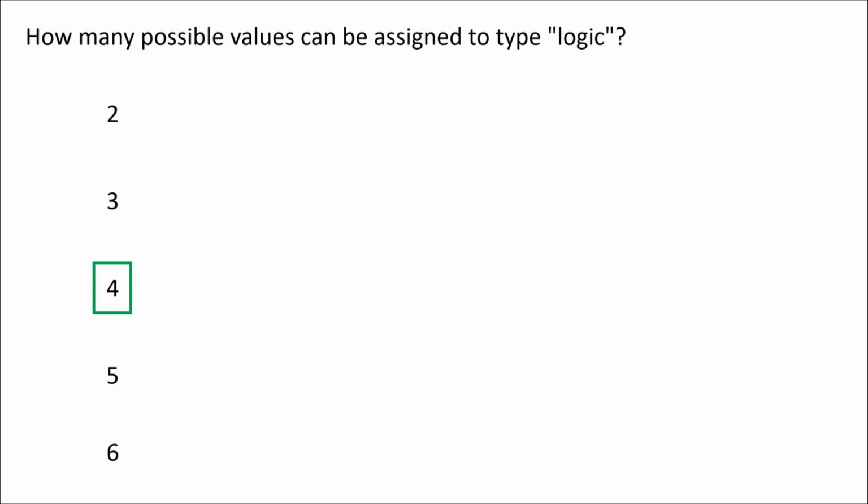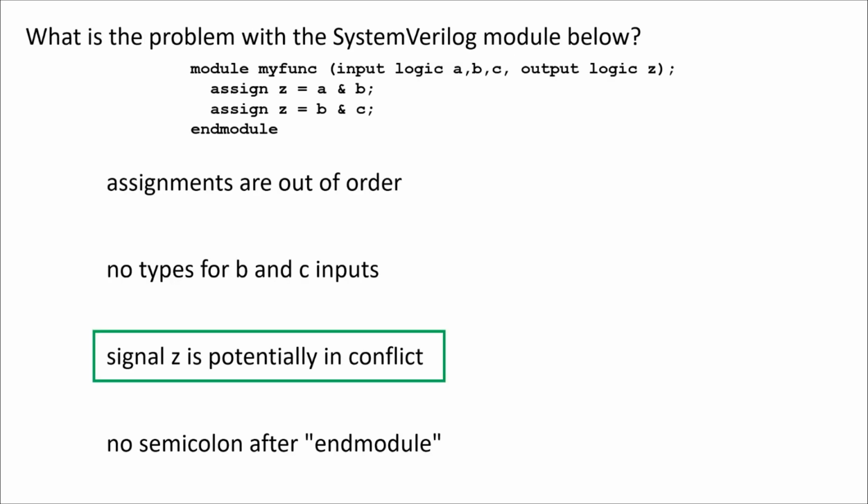You still can. In fact, you'll notice if you use the simulator, which we're not actually going to do in this class, you'll do that in 611. This class is just an intro to SystemVerilog. I'm just giving you a quick and dirty introduction. In 611, we'll be actually simulating SystemVerilog in a simulator. And in the simulator, if you don't assign an input, like say you simulate a module like this and you don't actually set anything for A, B, and C, like no one's setting that, there's no stimulus, right? Those will actually get a value of Z, which means they're floating. They're not being pulled down to ground, they're not being pulled up to VDD, they're just floating, right?